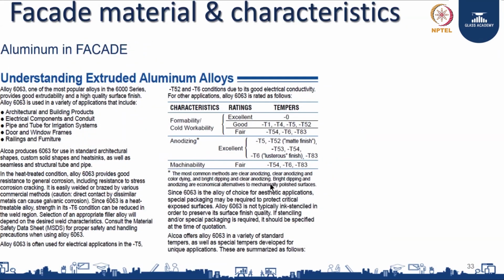When aluminum comes out of the extrusion process, the die process, it is soft like a sponge, you can crush it. So, you temper it, you make it stronger by putting it in an oven and heating it to the temperature where it can be made to your requirement. Commonly what is used for our industry is T6, which is a tempered alloy, where you still can work around it.